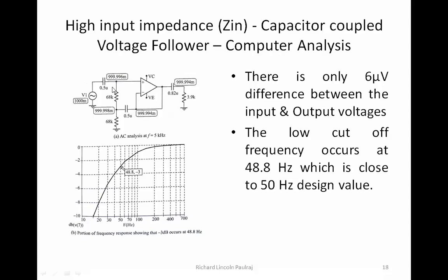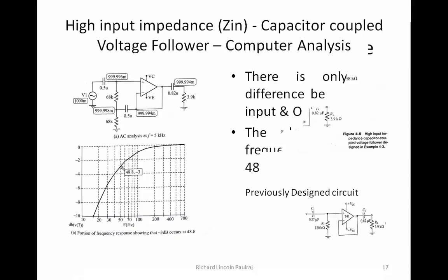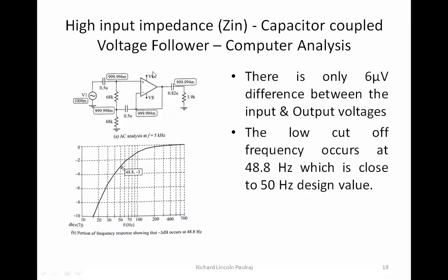then here, the capacitor which is on the feedback line, it's about 0.5, also at C1, right? So the same values, then plus and minus values. Now if we take the frequency analysis and take the minus 3 dB value, we have actually designed our system for 50 hertz, but then we are getting about 48.8, okay, 48.8.